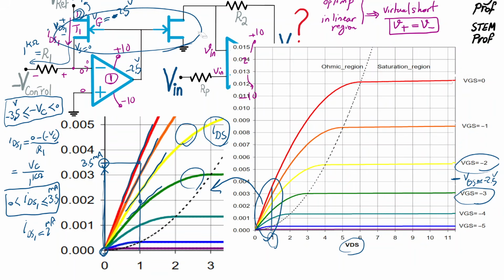When we say matched transistors, it means they are on the same substrate in the same package, benefiting from the same junction properties, and they have the same VGS. See, the gate of both T1 and T2 are the same, so whatever VG is set for both of them. And the source, so G and D, this is transistor 2, so we are dealing with VDS2 and the current is IDS2.